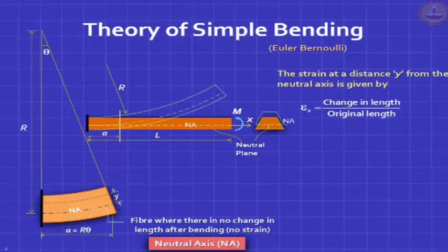So you define the location not only transversely as the height y above the assumed neutral axis. By the way, we don't know in advance where that neutral axis is. We are assuming there is some axis. We'll prove later that that axis can be easily located. It's a geometrical property of the section, but right now we don't make that assumption.